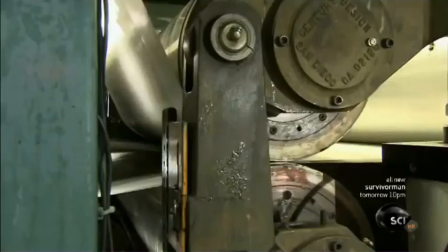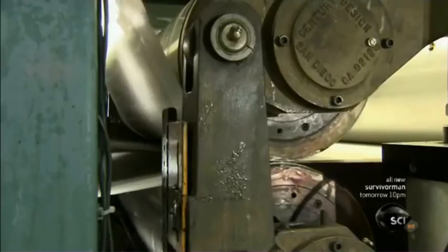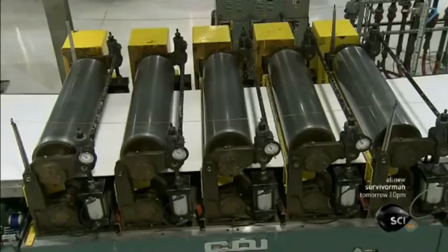A heating element warms up the web as it enters to facilitate resin absorption. Then, the heated carbon fiber web is sandwiched between 2 sheets of resin-coated paper. High-pressure heated rollers thin out the resin, so it penetrates the millions of carbon fiber filaments.